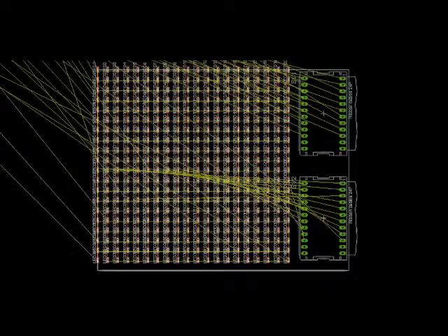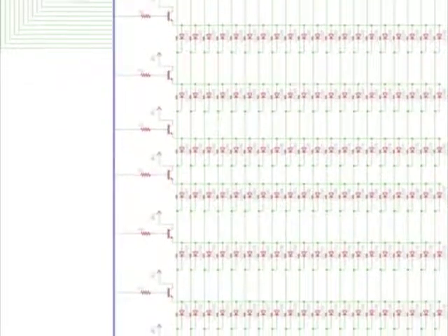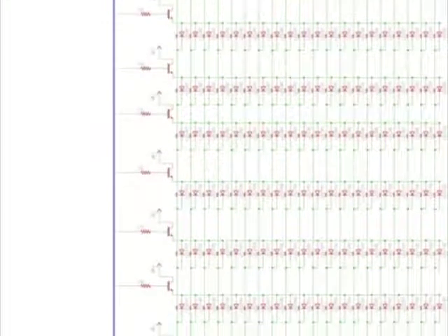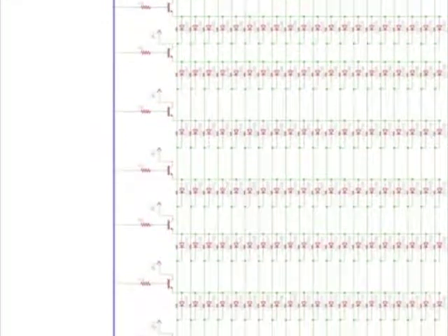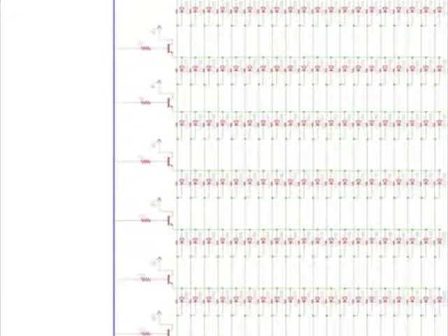The LED grid will be composed of either 3 25 by 75 grids or 9 25 by 25 grids. Experimentation is ongoing to decide which LED to use. Once the decision on which LEDs used has been made, traces of the grids can be planned. The LED control system is the most complicated part. The output of the ray triangle intersection algorithm will be loaded onto the apparatus using an SD card reader. This data will be interpreted by an Atmega 328 chip.